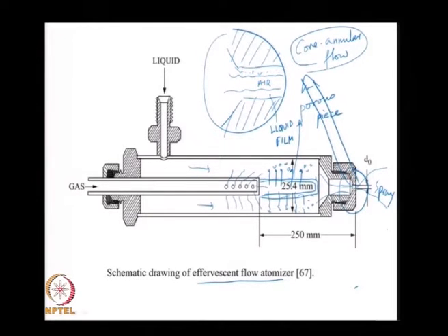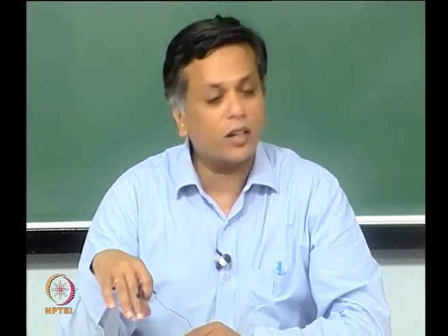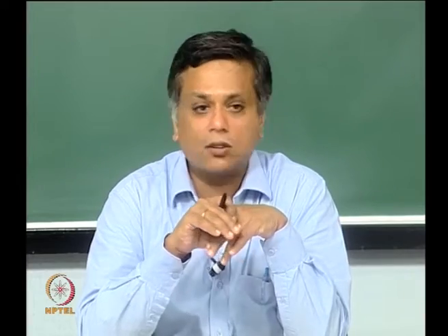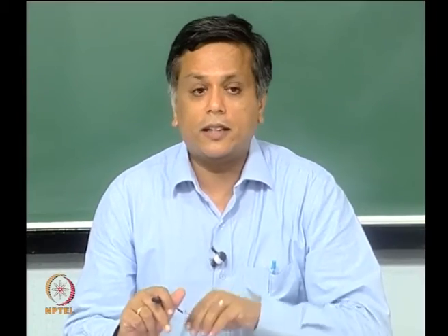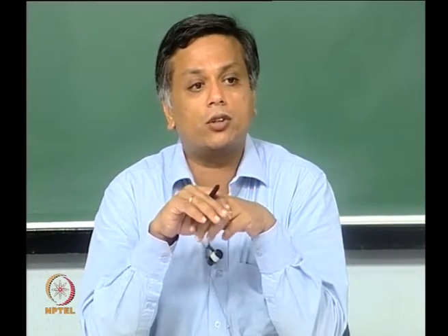This core annular flow design is like our old pre-filming air blast, because I now have an inner air, except in this case I do not have an outer air, but I can always introduce another outer air stream to this. But what people find is that is not required, because you are mixing the air internal to the spray nozzle. It is much more efficient at using the air for atomization.